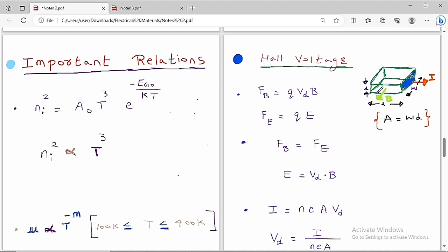Let me explain with a concept. Suppose you take an electrical wire, pass current through it, and keep that wire in a magnetic field. Then a Lorentz force is created on that wire. Same here also. In the semiconductor, you pass the current in one direction and apply the magnetic field in the other direction. Because of these two things, the charge particles present here are going to have some deflections, so a voltage is produced, which is called the Hall voltage.